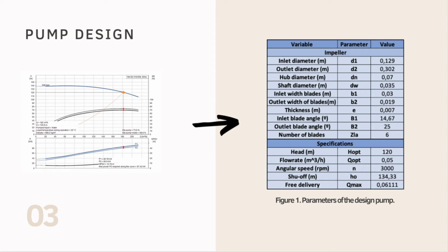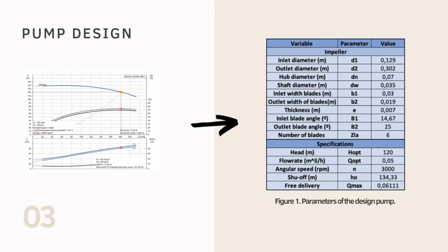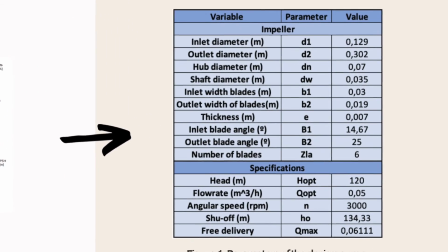For the pump design, it was necessary to obtain the efficiency, total head, and brake power curves using 2-degree polynomial regressions for the manufacturer's pump characteristic curves data. The model of the geometry was initially designed in a spreadsheet from the procedure specified by Gulich, which is a preliminary design based on the best efficiency point. In this case, the pump is designed to transport water and mineral oil. The main geometrical dimensions for the impeller, diffusers, and the specifications for the pump are presented in the next table.